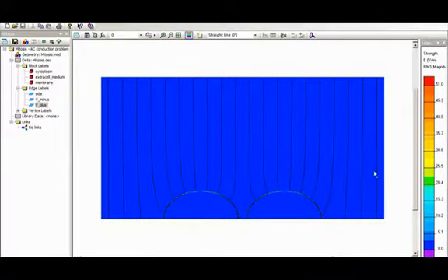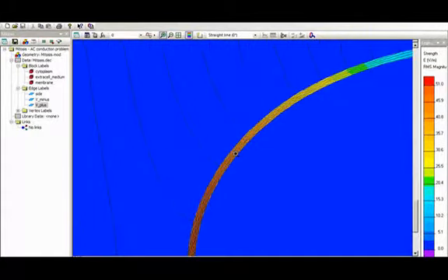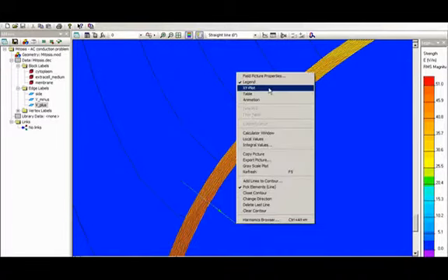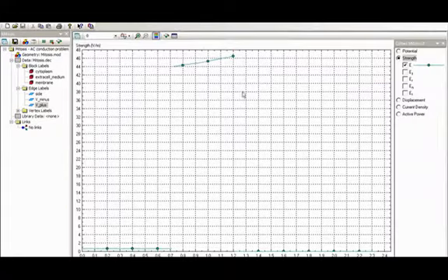And we can see that these are the equipotentials. The electric field lines are going to be perpendicular to the equipotentials. And the current is going to be flowing along the model here from the plus to the minus. The electric field and the current have been screened from the interior of the cells. And furthermore, we have an amplification of the external field across each cell. If I zoom in here, the color represents the electric field strength, so we can see that it has been amplified. If I make a contour that spans the membrane here, I can look at the field across the contour, and we can see that the electric field is very small outside of the membrane, and across the membrane is the induced electric field due to the electrical excitation. So this is different from the intrinsic electric field that we've looked at previously.